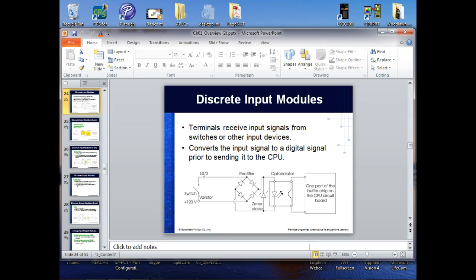And then we have a receiver over here. So this is a light emitting diode, an LED. This is a phototransistor, which basically picks up the light. That's why if somebody gets in front of you, your channel changer doesn't work. You say, get out of the way, right? You don't understand that because you're breaking the light. These are built in. You don't actually see this. But what it does is it allows us to do stuff over here. If we connected this input device directly to our peripheral control circuit and something happened, like a lightning strike out there, it would blow up my PLC. So we isolate it. They call it an optical isolator.